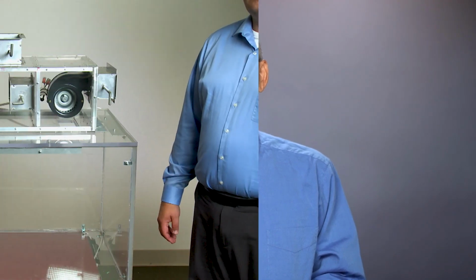In this case, the relief fan is shut off. But when the outside air damper opens further for airside economizing, this relief fan is turned on, forcing excess air out of the building and preventing overpressurization. John and Eric will demonstrate.